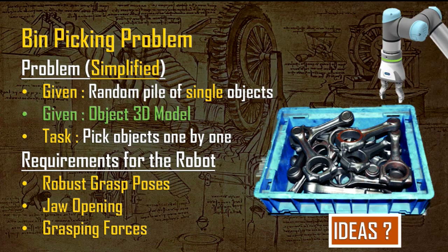Just one question: the entire requirement of having this depth information is because, as someone said, every time we pick an object from the bin, the distance will keep on changing, and for that we need this depth, right? Yeah, and it should be continuous. The depth has to be measured after each iteration of picking and placing because it would be changing.